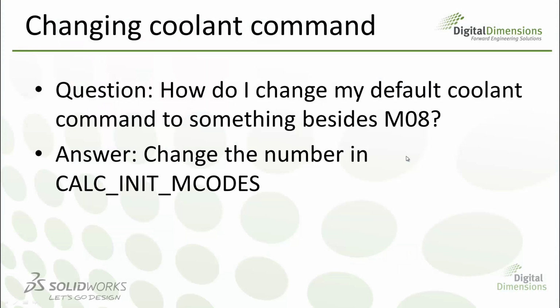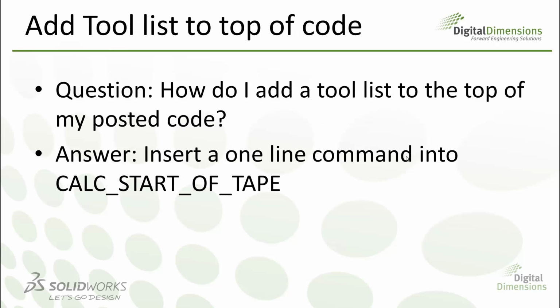So back to my PowerPoint, let's move on to the next question. How would I go about adding a tool list to the top of my posted code? It's a very commonly asked question. How do I go about adding a list of the tools at the very top of the code so that the programmer, whoever's setting this up, knows which tools to have, what order they're in, and so on? The short answer is I'm going to insert a one-line command into a section called calc start of tape. So let's jump into how I might accomplish this.